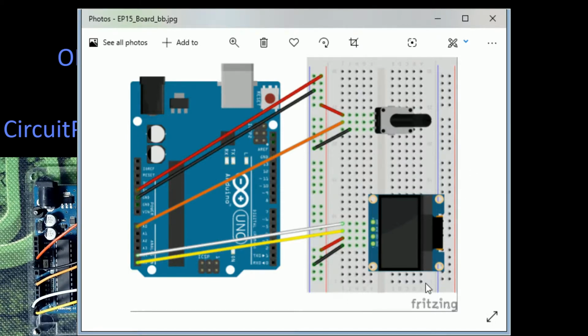So this is the OLED up here. And the OLED has the 4 connections on it. And I've wired them up. Now you can actually read those if you really want to. They're a little blurry. These images are rather small, but this is in Fritzing. I created these. These are just in Fritzing. I created this drawing yesterday, just to show you how it's connected. So I take my power, my 5 volts, and my ground connection from my Uno and connect it to my board. I go ahead and connect them to the device.